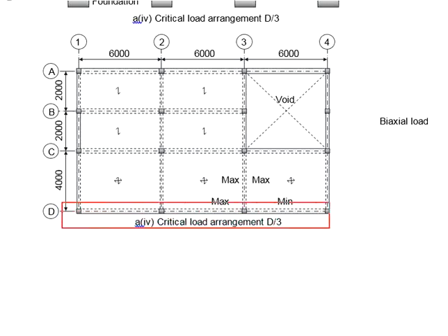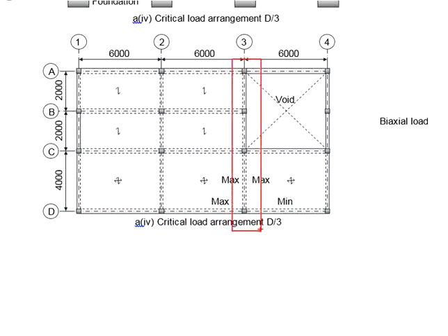Having these directions settled, we look into this frame here. Since you have no beam here and no slab here, that means this side of the column is not contributing any load. To get the largest moment possible, you will need to make these beams take the maximum UDL.